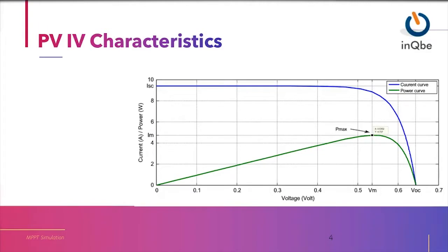Without load, there will be a voltage. Then that voltage will decrease with increase in load, step by step, linearly up to a certain level, and after some time it will decrease very fast, exponentially. It is almost similar to the IV curve of a diode, because it is a PN junction device, but the forward voltage will be higher than a normal diode.